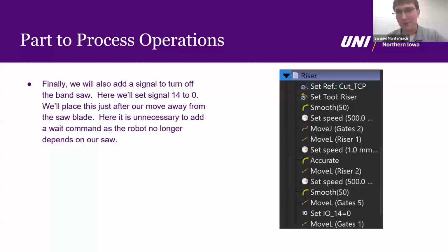So that's just one of the simple operations we can do with some offline programming. It's a pretty efficient process. Some of the nice things that we get to do with this is we can set very consistent cut lines and commands. And this is all based off of some of the stuff we did our very first time in the first workshop session, where we were setting up the location of our parts and the location of each of those individual tools used by the robot.